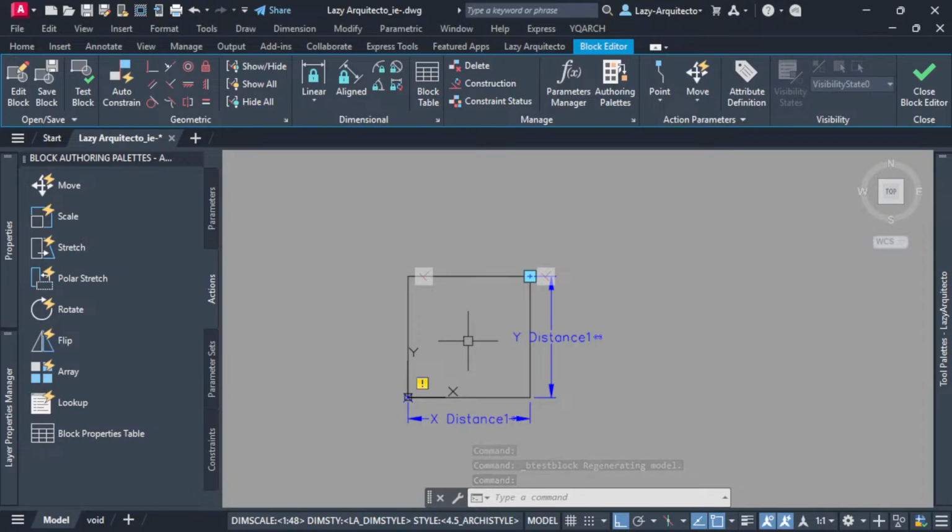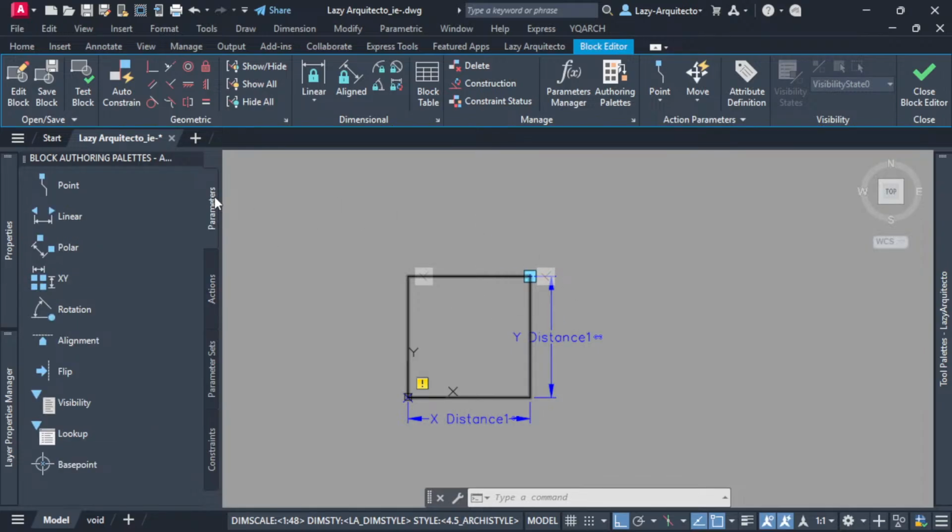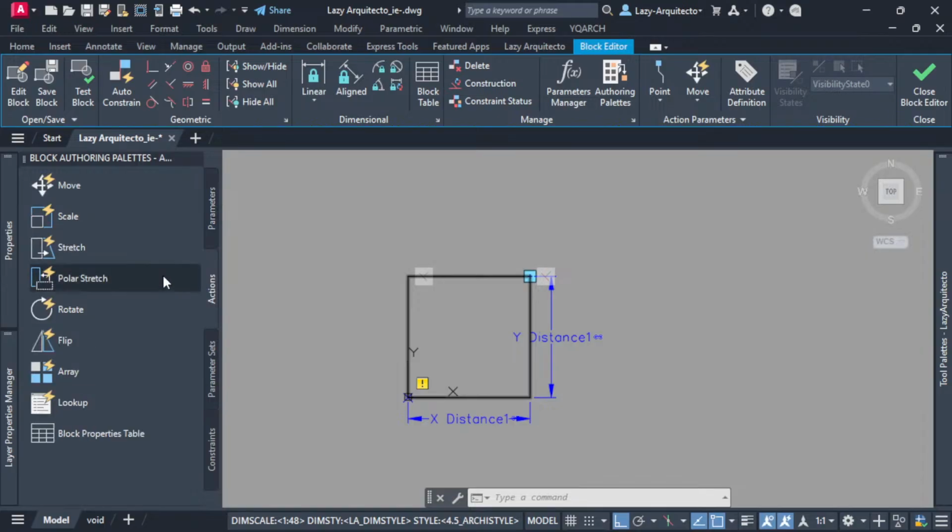Before I add any constraint to the bottom portion of my rectangle, I'm gonna apply the stretch. Again, the order is very important. That's why we were having problems. So let's try this third method. Hopefully it works. So I'm gonna add the action, the stretch in this case, again, only with the two perpendicular constraints on the top, nothing at the bottom.